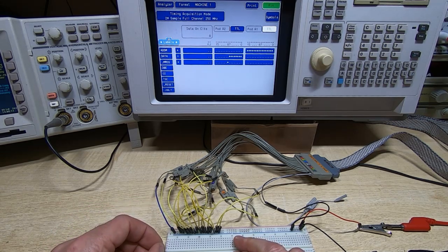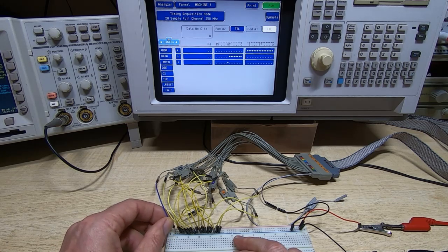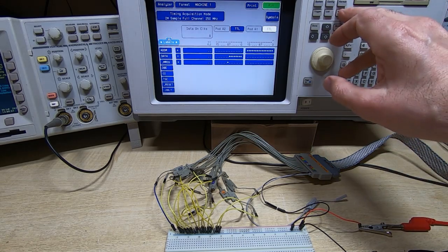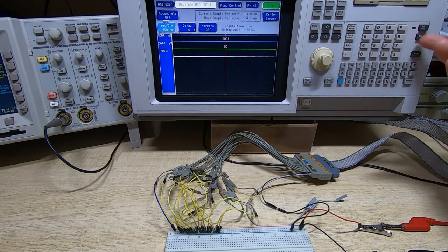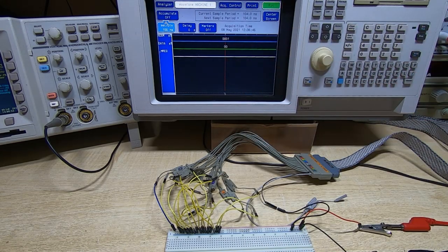If I move that bit to ground, you'll see that that will briefly show an arrow and then show ground. And if I move it back, again you'll briefly see an arrow and then it will show a high. If we capture data, and again I'm still on timing mode here, so it doesn't need a clock, but notice now that every time we run we are getting an address value of 1, which is correct of course.